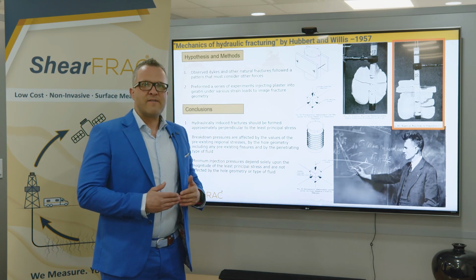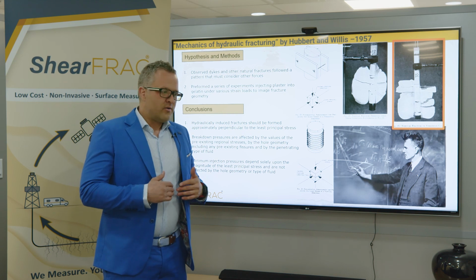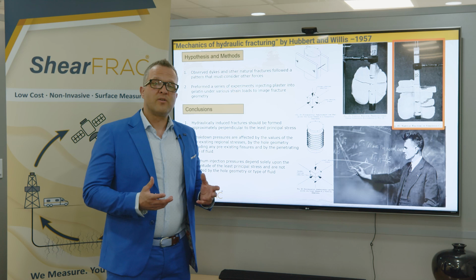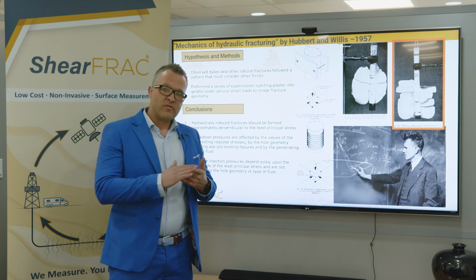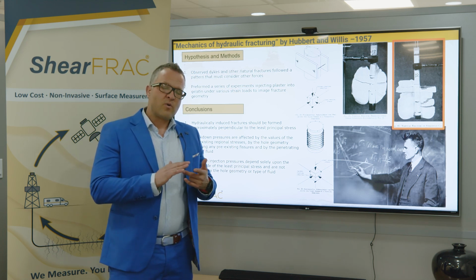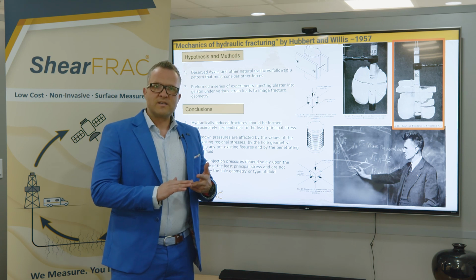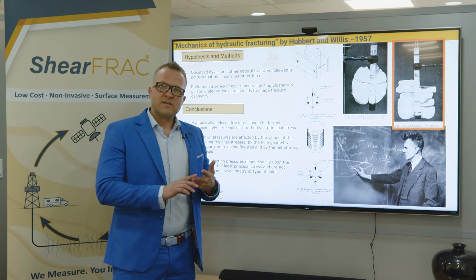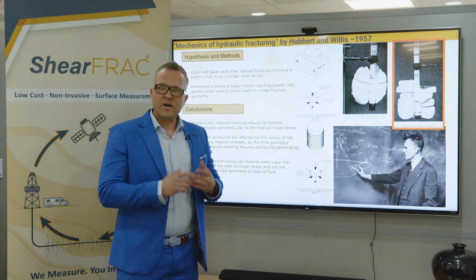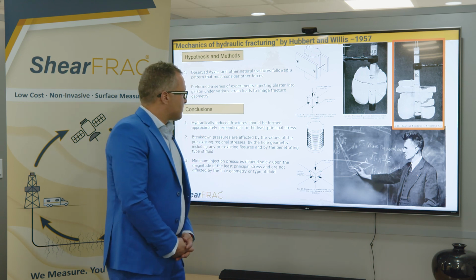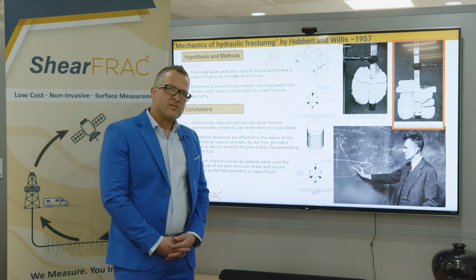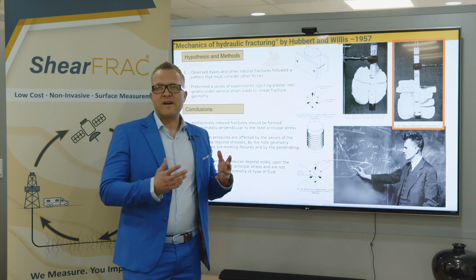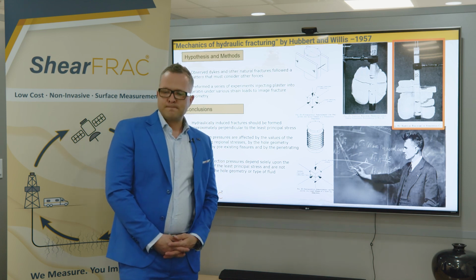What we're going to do now is take Hubbert's theory from 70 years ago, 1957, and apply new laboratory techniques, the best we could procure in the world. We're going to replicate real resource rock, real reservoir rock under real reservoir conditions, and simulate an open hole single stage slickwater frac, and see the results. Then we're going to move forward and see how we can take those results, apply them to the field with a new open mindset, and see if they actually yield better production.